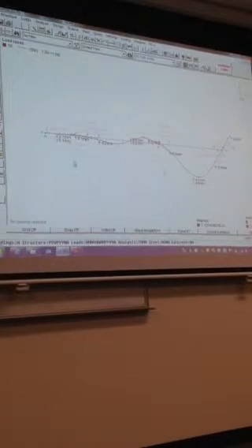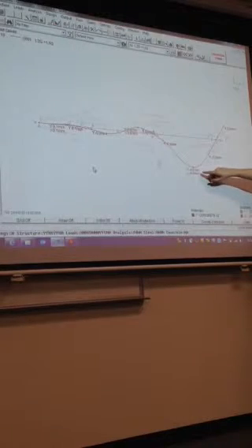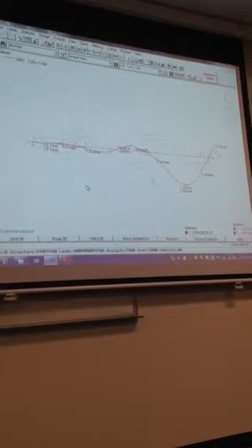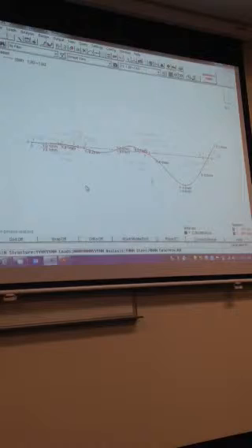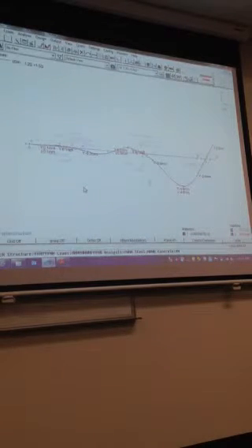The other thing which this will give us, and this is exaggerated, and we're going to be using this as part of stage 2, is the deflected shape. There are two things to remember about this shape. One thing is we're using the uncracked section properties of the concrete. We describe those as the gross section properties of the concrete. So our long-term deflection is going to be a lot more than this, but at least it gives you an idea. We can use this and proportion it, so we can estimate what we think the cracked properties are going to be, and proportion that deflection to suit.